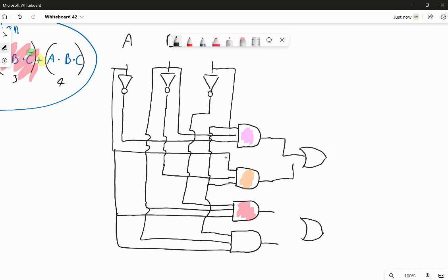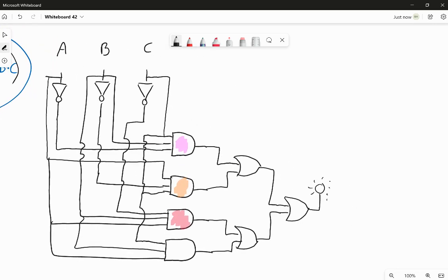So we'll have the top 2 gates feed into this OR gate, bottom 2 gates feed into this OR gate, and then our final 2 outputs will feed into another OR gate. Hopefully this will work fine and it will go out onto our logic probes. Now don't forget, when you build this on Multisim, you will need to put some switches into the top of your circuit. Hopefully you've saved the circuit from the previous week and you can just copy and paste your switch configuration from there.